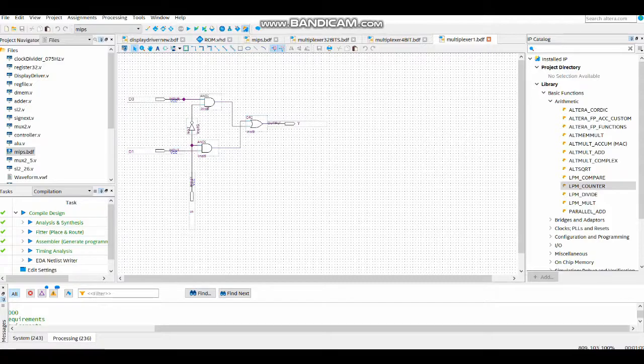It is built using two levels of logic, which comprise two AND gates and one NOT gate, and the output is combined by using an OR gate. It can also be built from tri-state buffers, arranged such that exactly one tri-state buffer is active at all times.